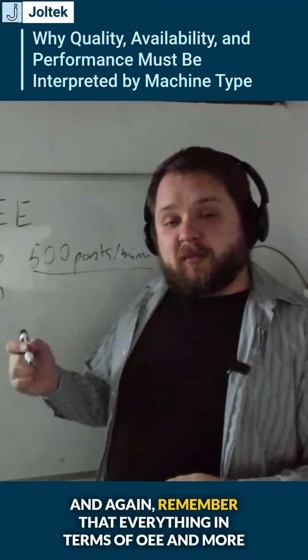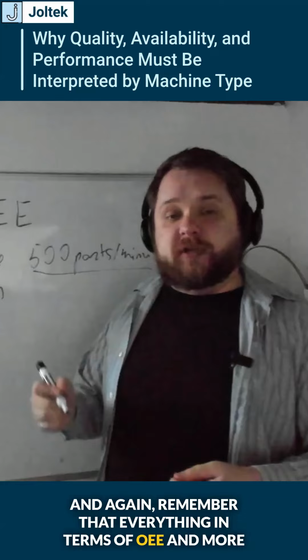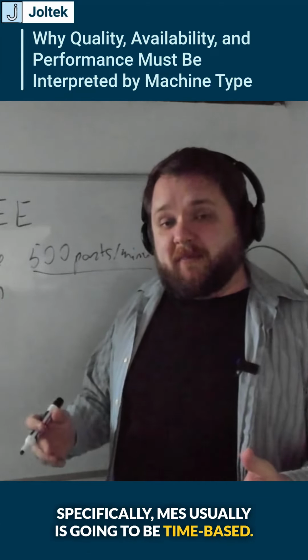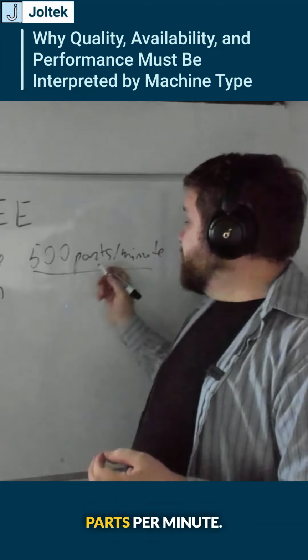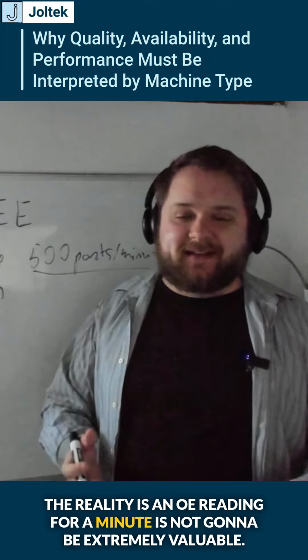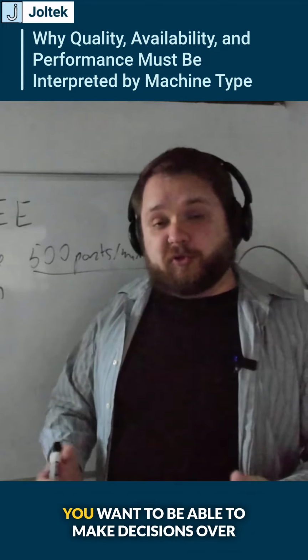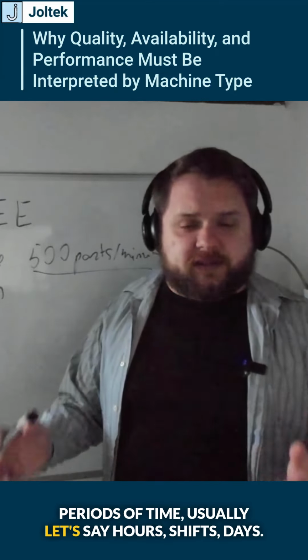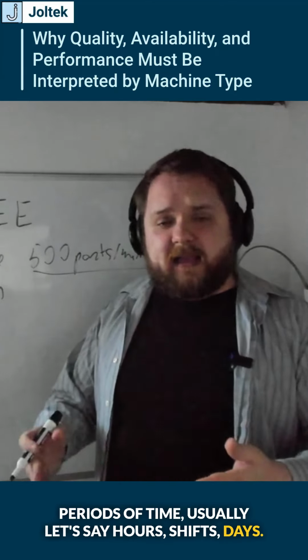And again, remember that everything in terms of OEE and more specifically MES usually is going to be time based. So here, when I'm talking about parts per minute, the reality is an OEE reading for a minute is not going to be extremely valuable. You want to be able to make decisions over periods of time, usually, let's say, hours, shifts, days.